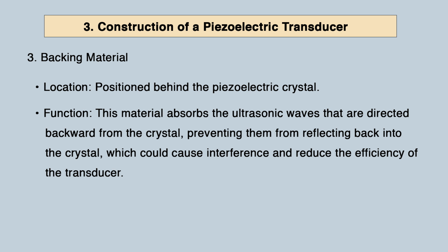Backing material is the layer behind the piezoelectric crystal. This material absorbs the ultrasonic waves that are directed backward from the crystal, preventing them from reflecting back into the crystal, which could cause interference and reduce the efficiency of the transducer.